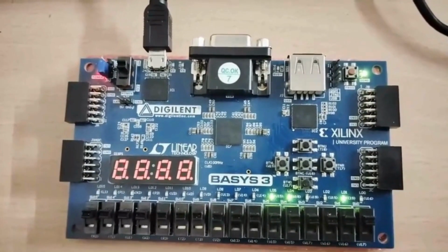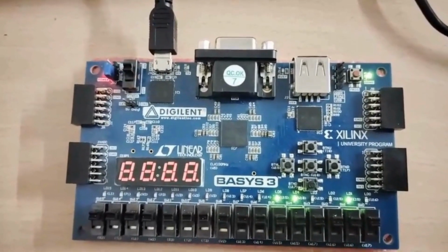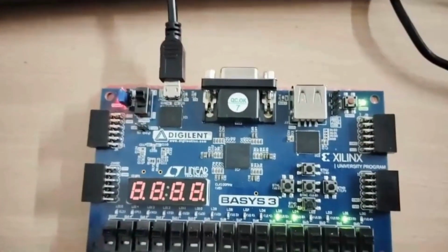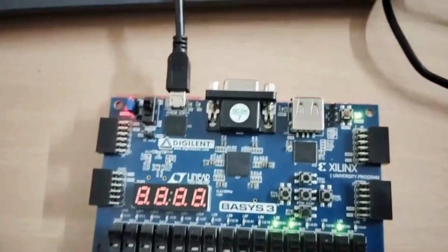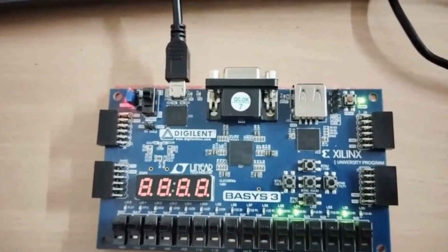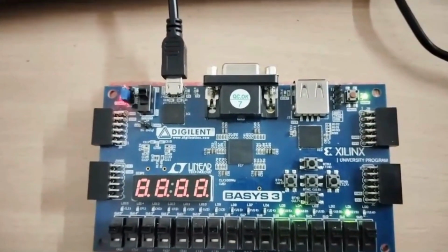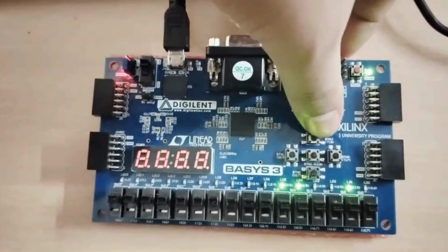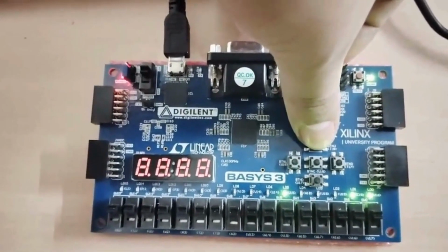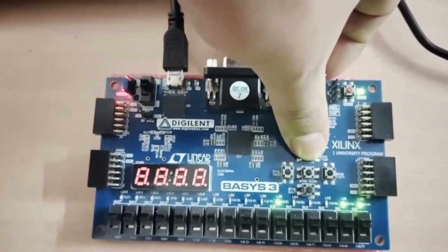Basically, the lower nibble and the higher nibble of the 8 bits will be exchanged. So what is a lower nibble? The lower nibble is four consecutive bits ending at the LSB, and the high nibble is four consecutive bits in an 8-bit binary string starting from the MSB. So the operation is like this. As you can see, the first four bits are swapped with the last four bits of the 8-bit binary string. So this is our Lab 2 and 3, which is demonstrated successfully.